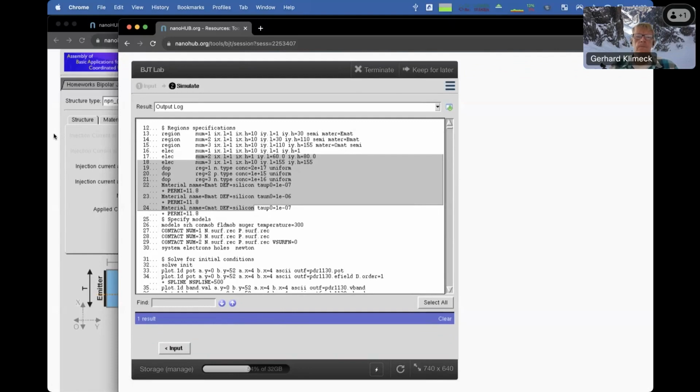And the next question, someone asked, what about the material library? Yeah, so Padre knows about silicon, germanium, gallium arsenide, the typical semiconductors. This tool predates graphene and 2D materials, so it'll know the standard semiconductors and has mobility models for them. And this is all drift diffusion. Padre is drift diffusion. If you wanted to have quantum transport with different materials, that's a different ball of wax. We can do that.